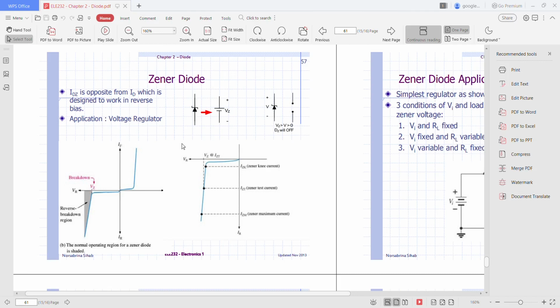First, the state of the diode must be determined, followed by a substitution of the appropriate model and determination of the other unknown quantities of the network. Okay.